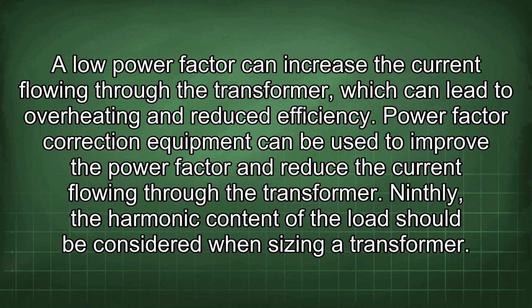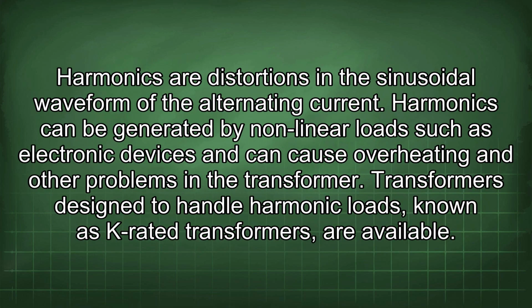Ninthly, the harmonic content of the load should be considered when sizing a transformer. Harmonics are distortions in the sinusoidal waveform of the alternating current. Harmonics can be generated by nonlinear loads such as electronic devices and can cause overheating and other problems in the transformer. Transformers designed to handle harmonic loads, known as K-rated transformers, are available.